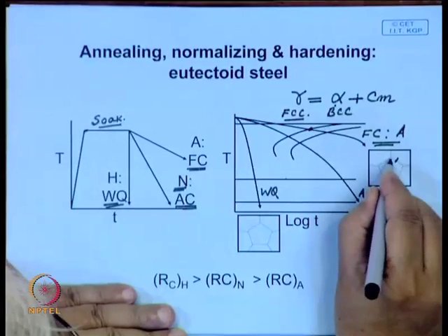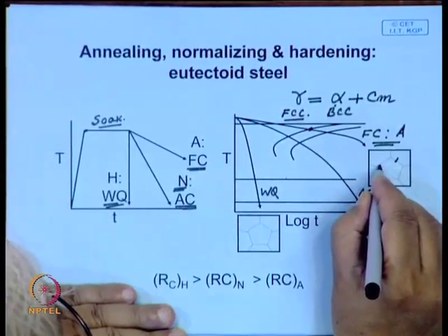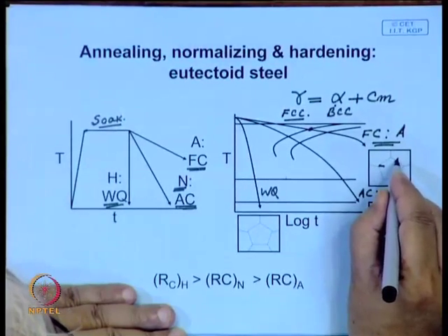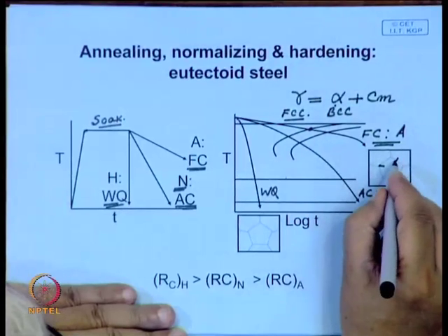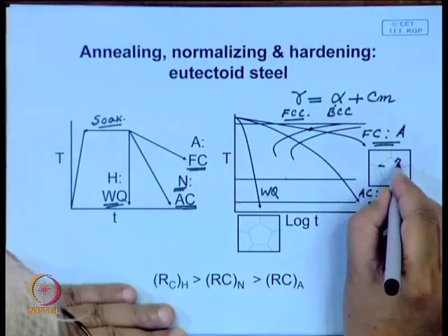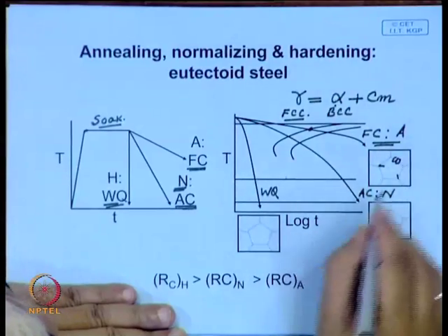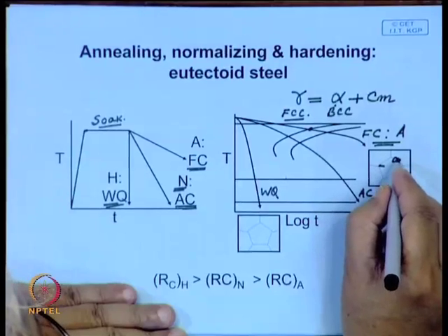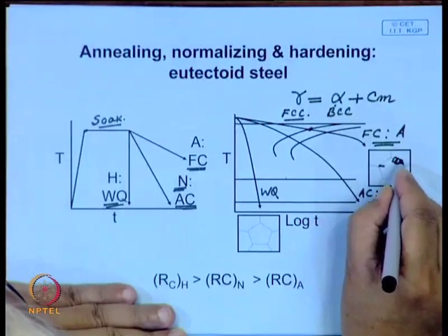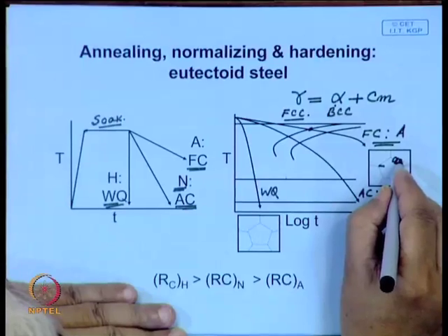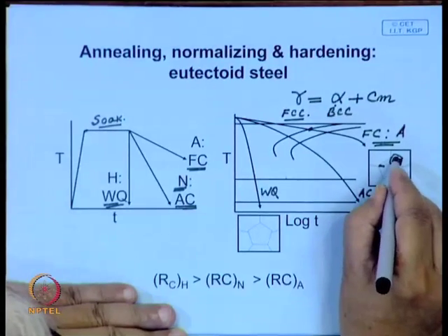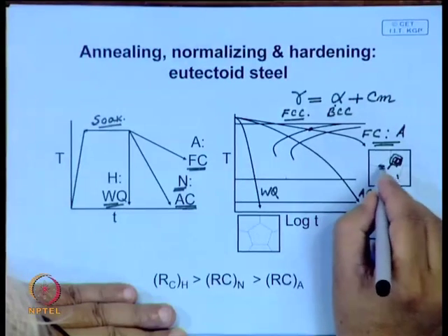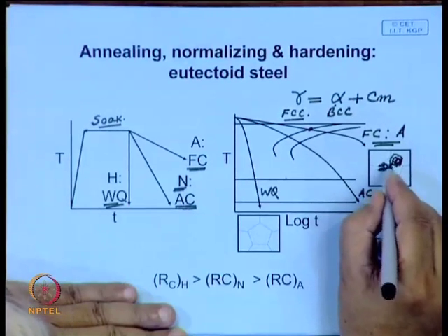and when this happens, you have a nucleus of cementite forming at these interfaces, and when this forms, the surrounding region gets depleted of carbon content. Therefore, simultaneously a ferrite plate or a ferrite grain will nucleate just beside the cementite, and this process goes on, and this is called pearlite, and this grows in all directions until it meets another such pearlitic region.